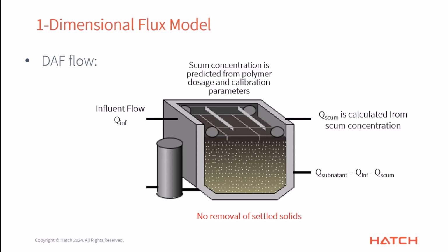So if you're in a situation where you know solids are being removed from the influent flow, settling out and going down, despite the fact that the bubbles should be pushing them up to the top, but they're heavy enough that they fall out, you could very easily put another solid separation unit right in front of this one. Just grab that black and blue generic dewatering unit, remove a bit of the solids there, and put the rest of it in here. We're going to combine them together at some point, but for now, that's how you would treat that issue.